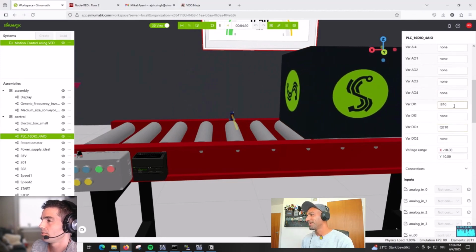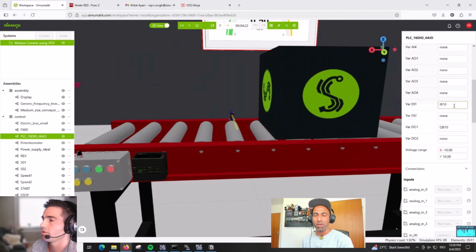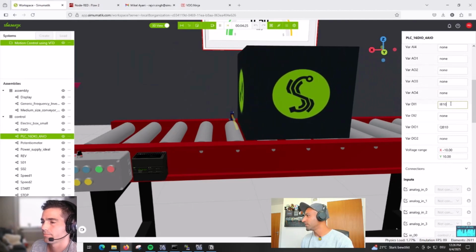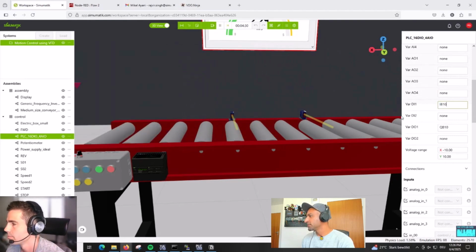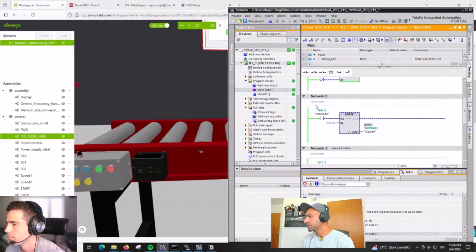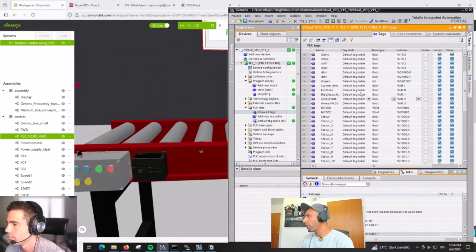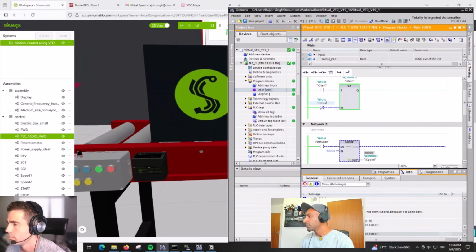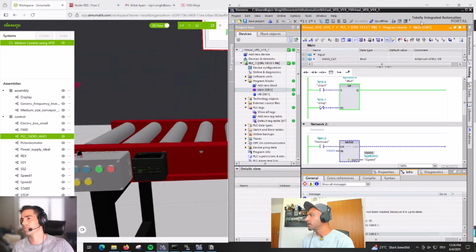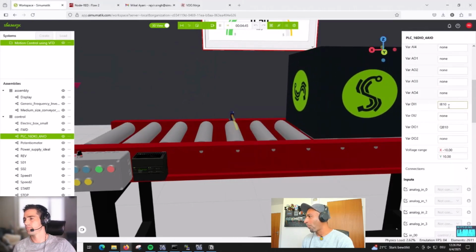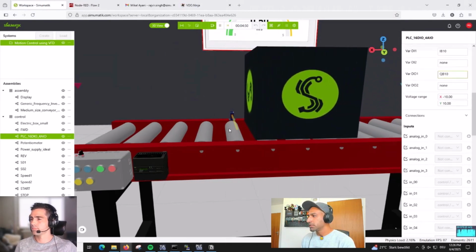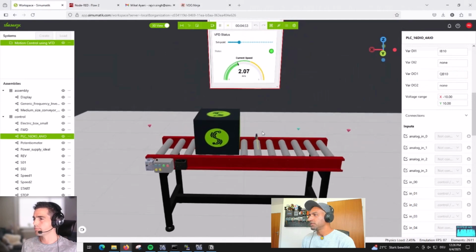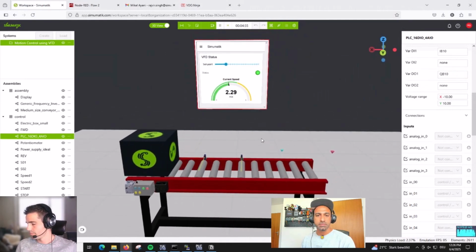Yeah. Cool. And here was the variable that I mentioned, IB10. So all the inputs that are coming from Simumatik are going to be at the byte 10. So if I show you here, I'm using, I think I didn't mention here, but I can show it in the main block. I'm using I10.0. So this 10 has been defined because of this variable. And for the output it is QB10.0. Anyways, we are not using outputs. That's how the PLC, VFD, and Node-RED are interacting for the simple motion control application.